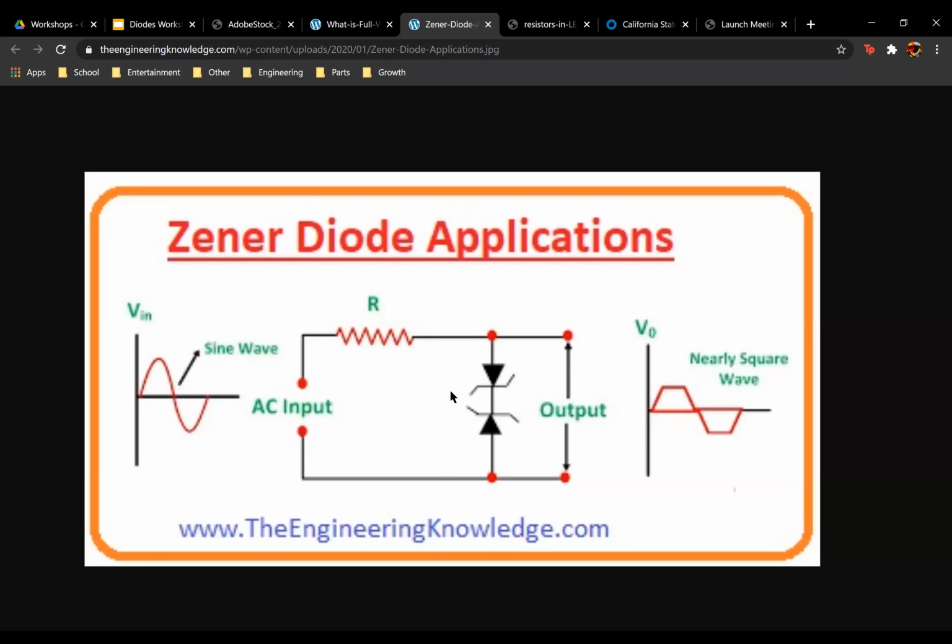It's going to create this behavior. And basically what happens is it's going to act as a diode protection circuit. I'm going to use numbers right now to explain it, but we'll say that this particular Zener diode is rated at 8 volts. What that means is if 8 volts is applied to this Zener diode in reverse bias, then it's going to Zener. So basically, we know that if it's Zener, you're going to have 8 volts.